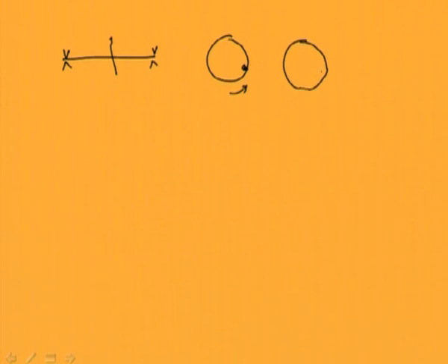So if it is stopping somewhere here, and in the next attempt also it is stopping at the same position, that means the unbalance is somewhere here, which is trying to stop the rotor at the same position. If this position is different all the time, sometimes here, sometimes here, that means the rotor is balanced.